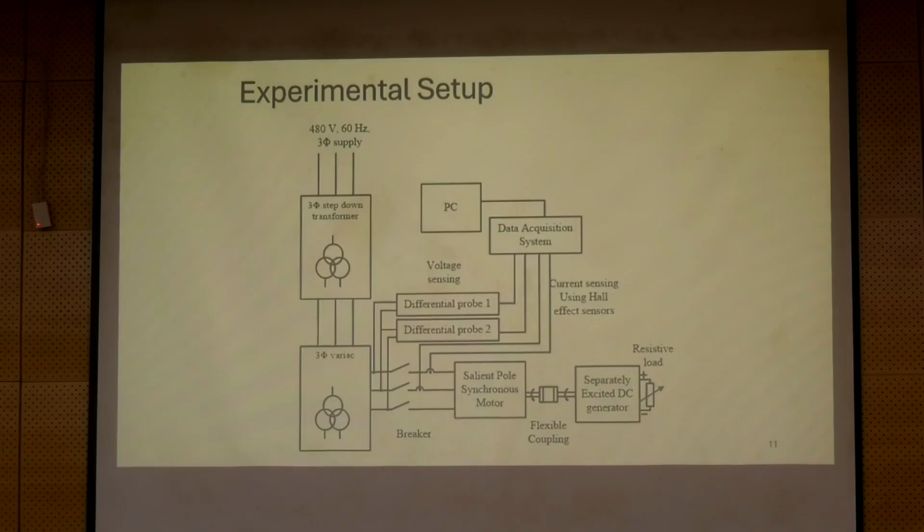You will have a supply from the utility that is feeding the motor. You will have a variac, and after the variac you will have a three-phase inverter. And typically for a permanent magnet motor, you will need to sense the position of the rotor and create a closed loop to drive the motor. Okay, so it's a little one step more. So you need to know how to do that inverter driving of a PMSM before you can get into the actual data collection process. Okay, so these are a few things.